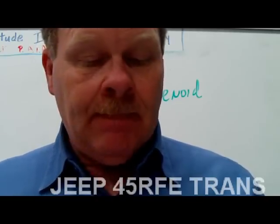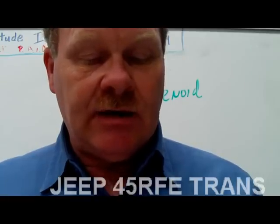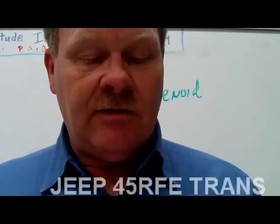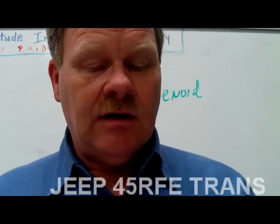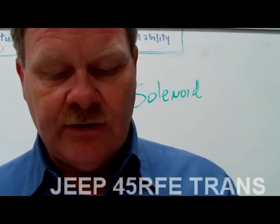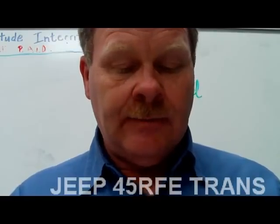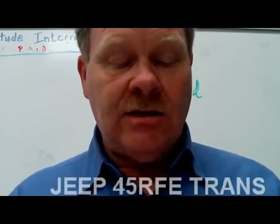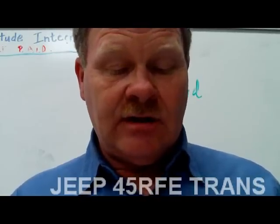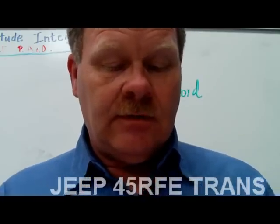All right. Now then, which of the following valves is not located within the dual stage pump assembly? A, manual valve, B, converter clutch switch valve, C, pressure regulator valve, or D, converter clutch regulator valve? Which one? Come on, guys. Manual valve's the one that you move whenever you move your gear selector. Your shift lever moves the manual valve. True or false? The middle of the operating range on the transmission fluid dipstick is the target level on a hot transmission. That is true. If the shift lever is in the drive position and the 45 RFE transmission goes into limp-in mode, what gear will the transmission be in? Third. That's right.